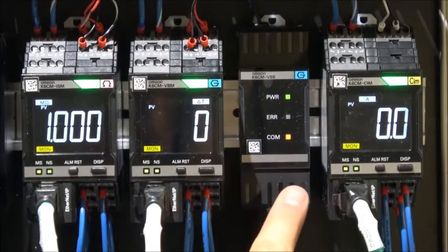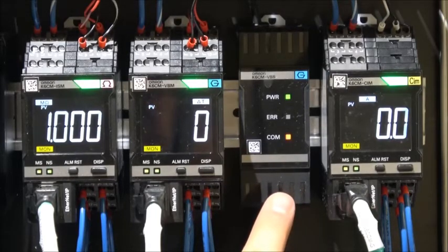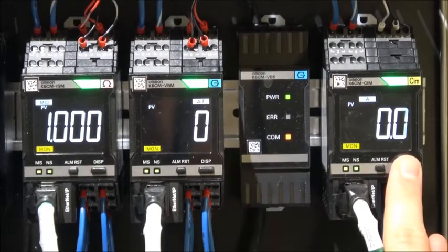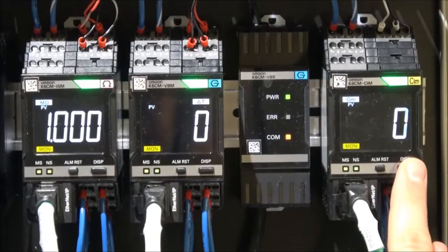Right here is our vibration amplifier, which is also measuring the ambient temperature to compare to in the delta T. And lastly, the current analysis will show the current as well as the degradation level, the deviation from a uniform sine wave that will result in some kind of warning or critical threshold.